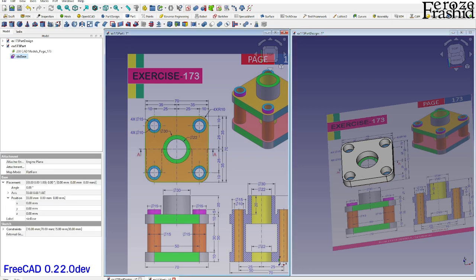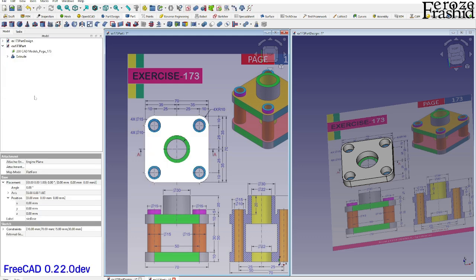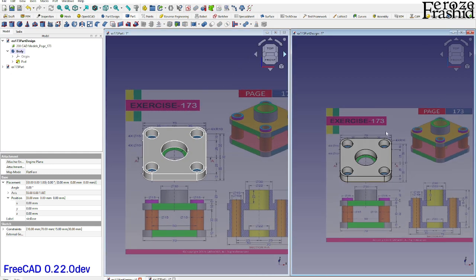Now having this set up as tabs like the Microsoft Word interface makes it easier to switch between different work groups, which are called workbenches in here. And I think this makes more sense. So I come to Part, take the sketch, and then make an extrusion of 10. The first difference between these two is that it is called pad versus extrude in Part Design and Part workbenches, but it's essentially the same thing. So we have it there.